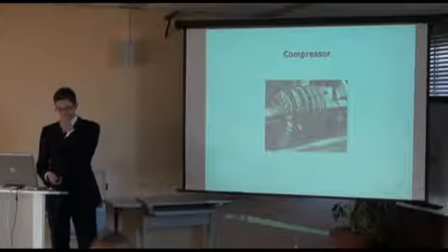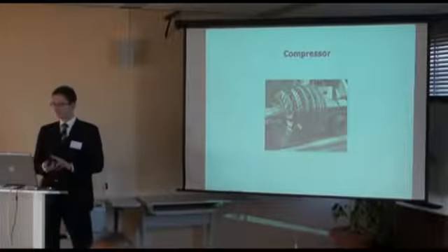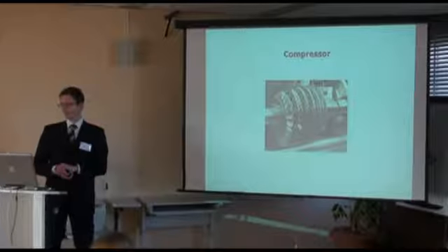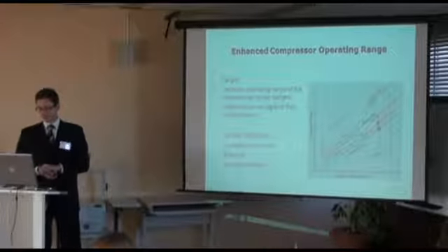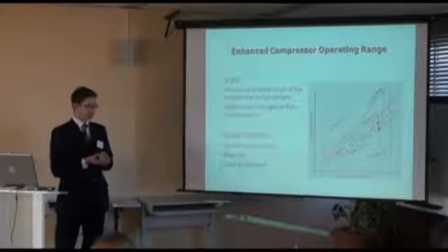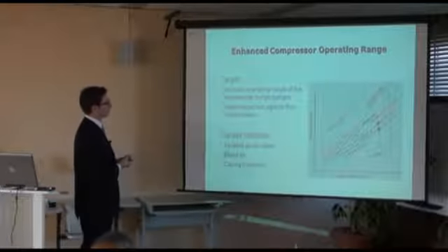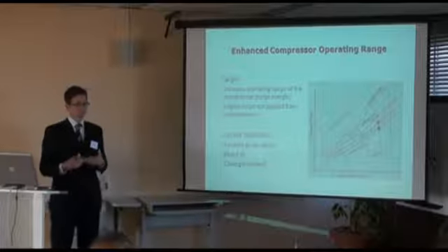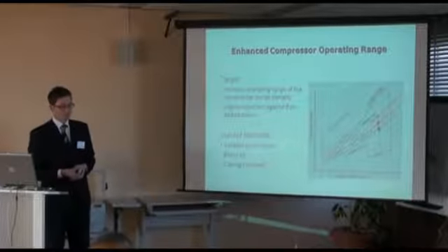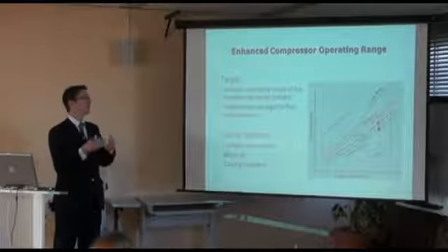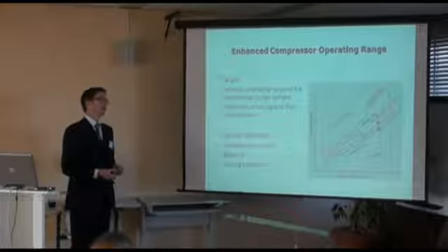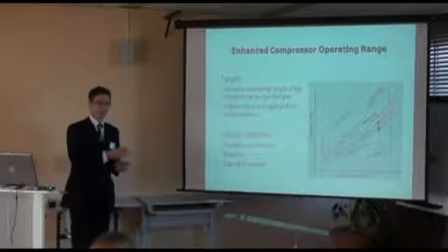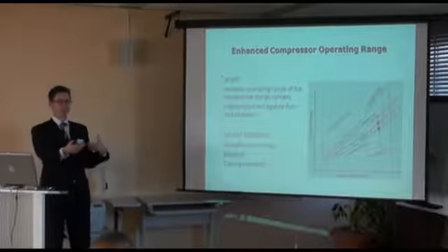Okay, the compressor. The compressor is a very interesting part in terms of flow control because it has some specific characteristics. You want to increase pressure by applying a pressure ratio, put energy into the flow, and then you've got the risk of a flow instability because the back end pressure is higher than the front pressure.